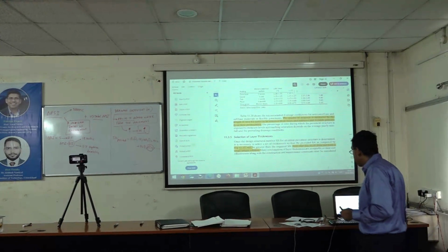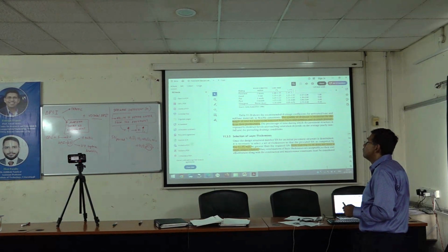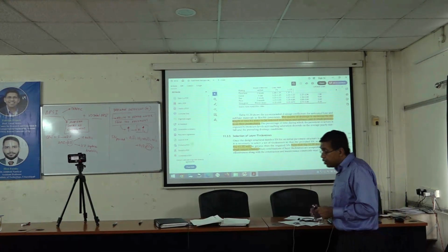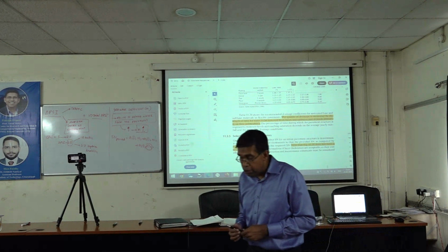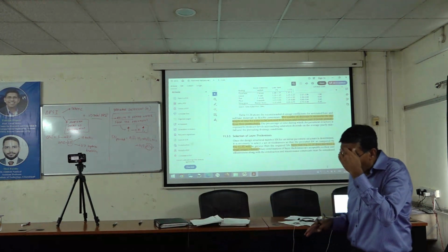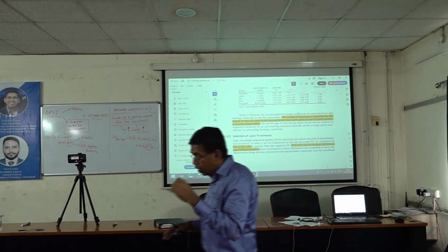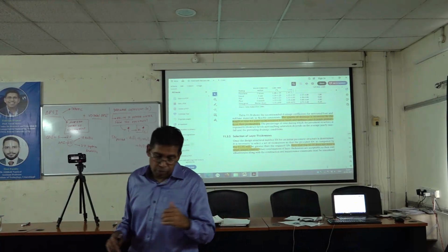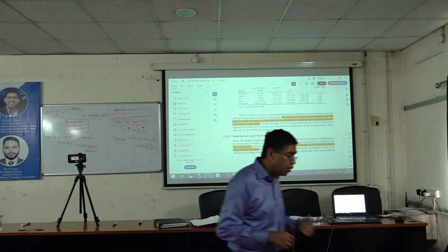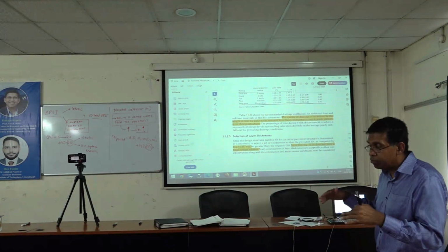So in that case, M2, M3 correspond to the granular layers. So is the capability to drain water not from the top surface through rain? The water could enter. You will have transverse slopes, but you want to make sure that the water doesn't enter. And if it is entering from the top, the voids are so low that it is inevitably going to get trapped.